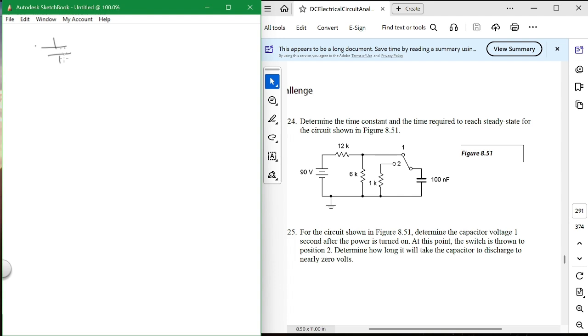So as you look at motors that start and stop a lot, what do you see? It's called pitting. And that's why after so long a time you have to go into a motor with a starter, a manual starter or one that opens and closes, and change out those contacts, because you cannot start and stop inductive current immediately.